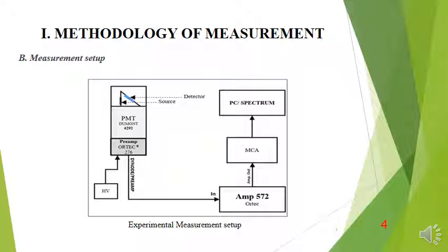The gain of the amplifier was set at defined values for both detectors. The shaping time of the amplifier was also set at the minimum value which allows the collection of the total charge created in the photomultiplier tube. This value also allows us to collect the total charge created in the detector, as powder scintillators are known as high photon scattering and self-absorbing materials because of their opacity.